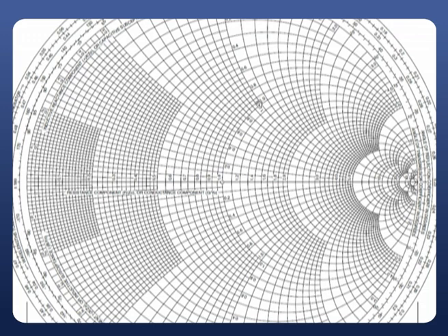This circle passes through the real axis, so on the real axis, clearly identify the value of resistance where the circle meets it. That resistance value is nothing but the standing wave ratio. So it is very easy to calculate using our Smith chart.